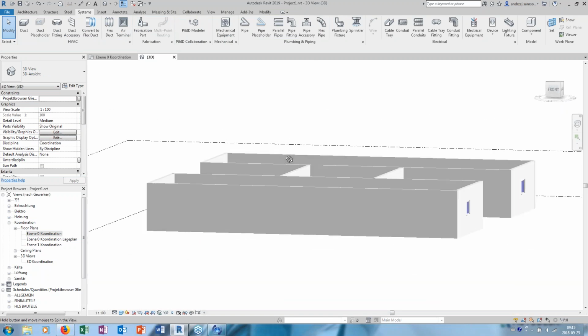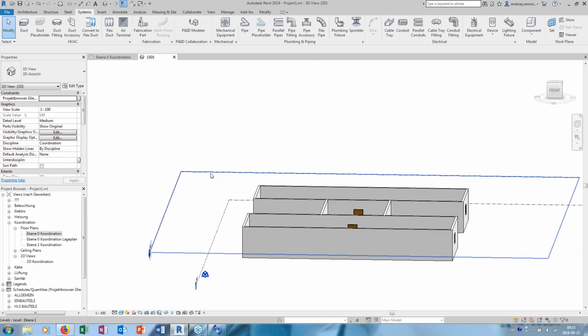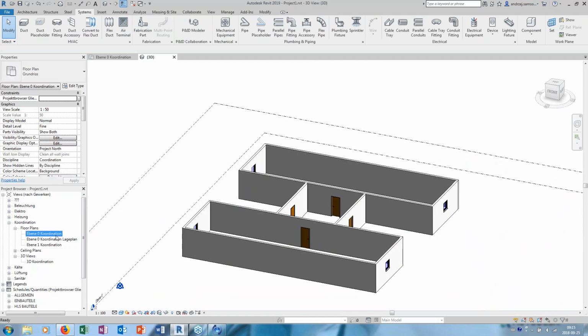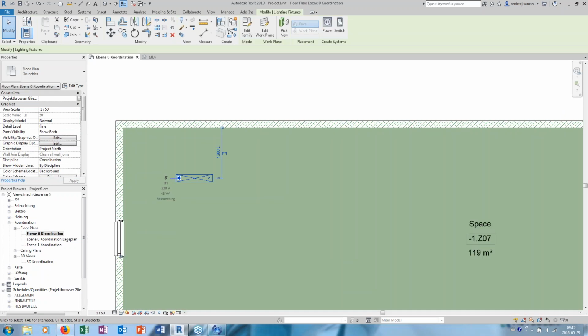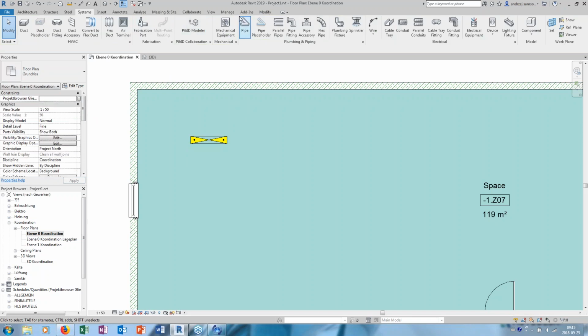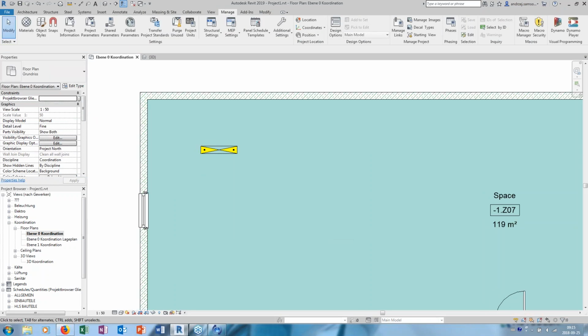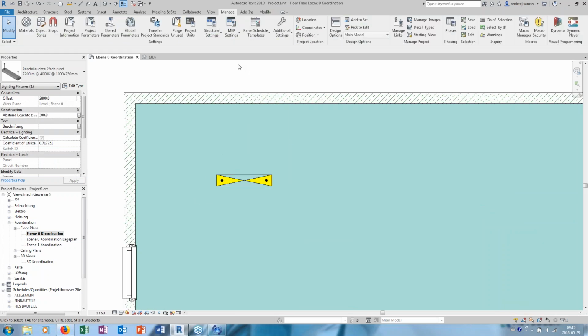If you look on the side, you can see that the Revit space is defined by these floors. So if I open my 0 floor and place my lighting fixture, it's laying on the ground. If I put it at 2,800 millimeters, and if you're not satisfied with the units, you can always change them from here, I have my lighting fixtures placed here.